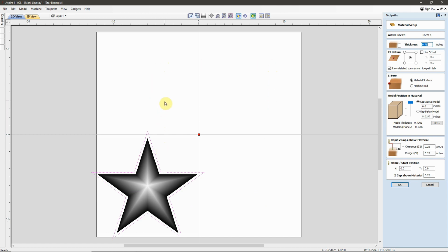What I'm talking about is either double-sided tape, or my favorite, tape and CA glue, or a vacuum table, or something of that nature. Because there's a possibility these could break loose after machining and before we create a profile cutout. So think practically as you're designing these projects.